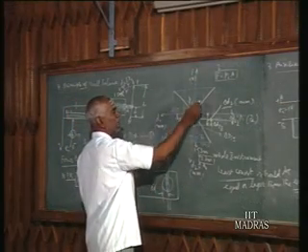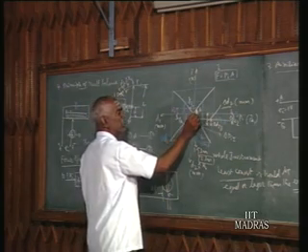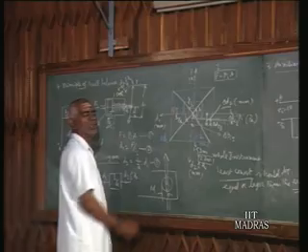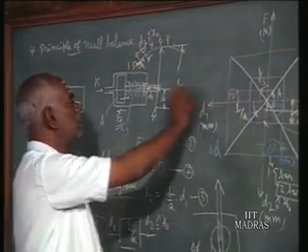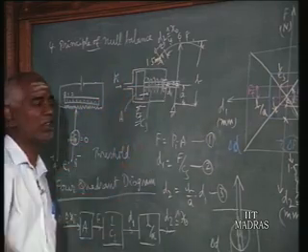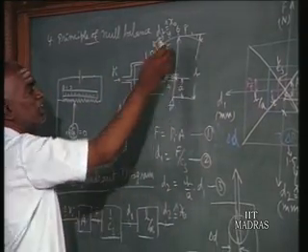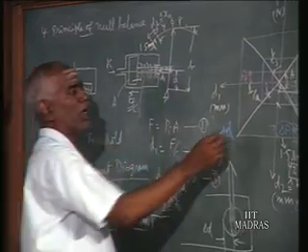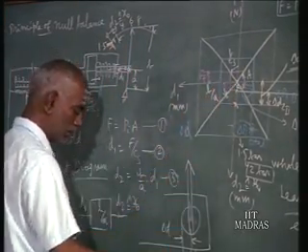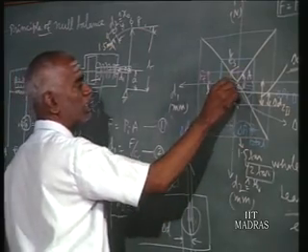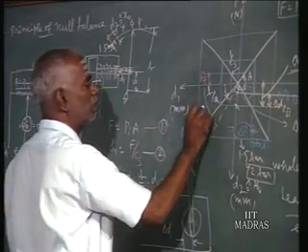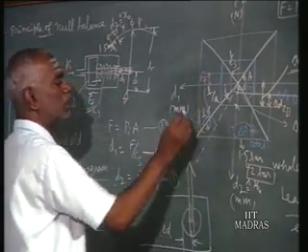By increasing the characteristics of the 3 blocks. That is, A can be increased to A dash, or 1 by CS can be increased to 1 by C dash, or the B by A ratio can be increased. Changing CS means you have to change the spring, and changing the area means you have to go for different types of cylinder and piston. They are very costly. So changing the leverage is simpler. So have a larger b or smaller a, and have another slope for it, that is our changed pointer, b by a dash.